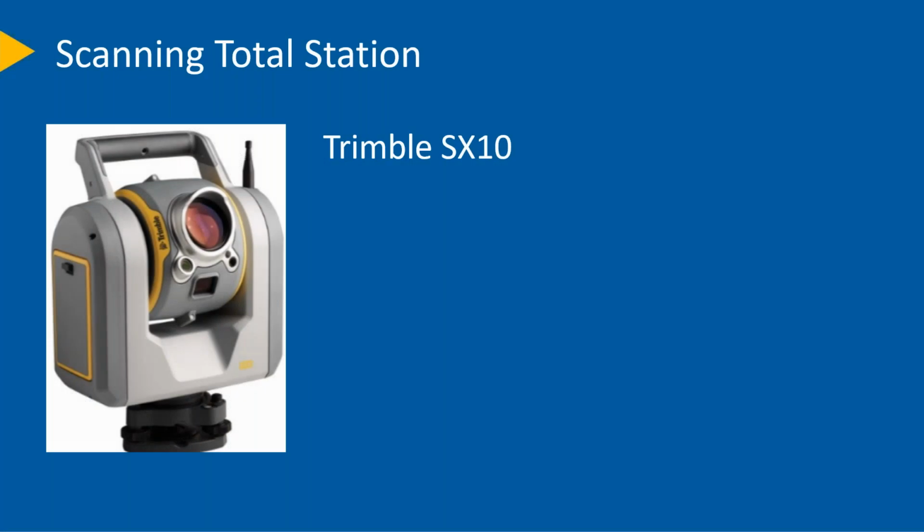Now, if you're a surveyor and you're just thinking of getting into laser scanning and you don't know when you might use the laser scanner, you might have seen one project or two projects or a couple instances where you thought having a point cloud could be useful. There's also another class called scanning total stations. This is an example of the Trimble SX10, where it's a full total station, but also has a laser scanner built inside of it. So these are very versatile in that when you're not doing a scan-specific project, you're also able to use this for all of your other survey requirements.